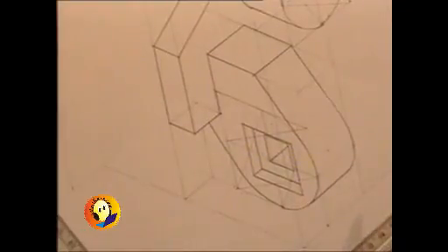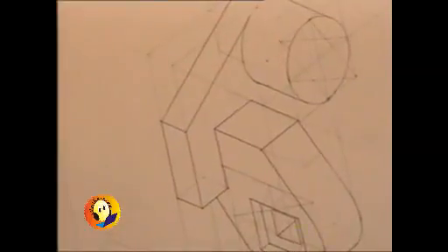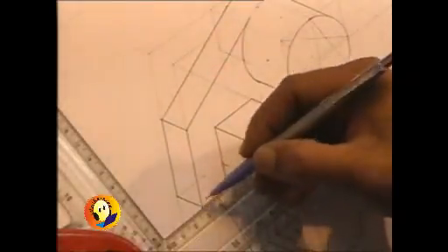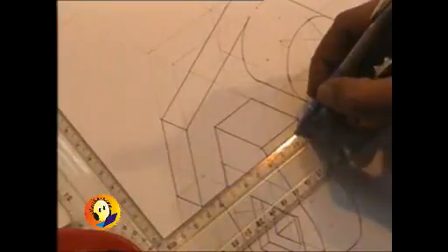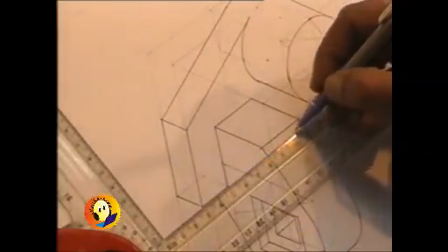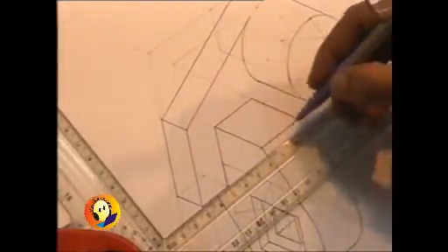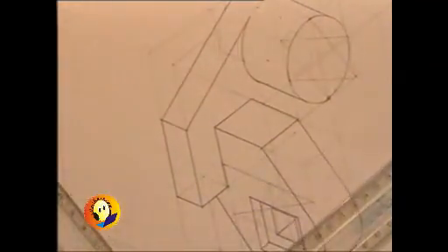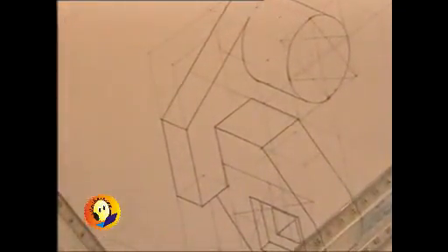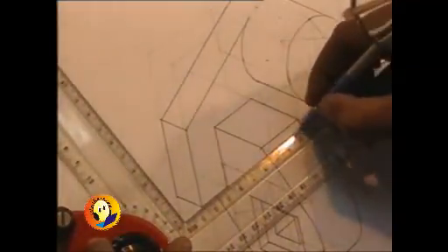Now let us go back to the portion where we are still required to show the rib, whose center is from this point at a distance equal to 75, and we have already seen in our previous construction that that point of 75 is going somewhere behind the block that we have already drawn. So this is that distance, the center 75, and the thickness of the rib was 6 millimeters, so I will be measuring 3 millimeters. This construction will be required,